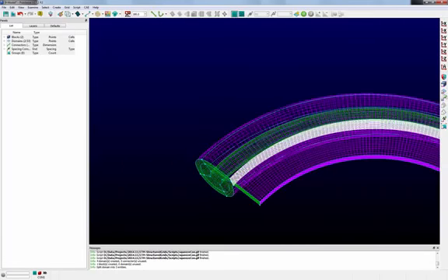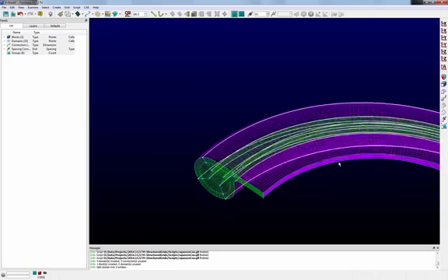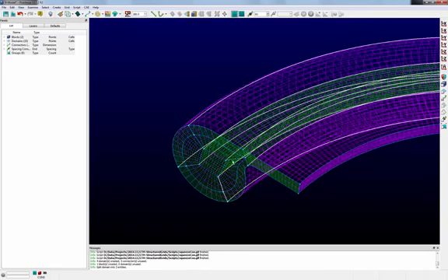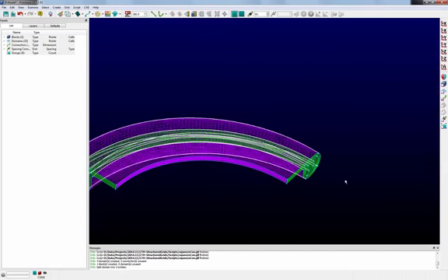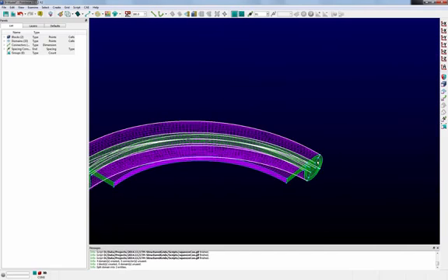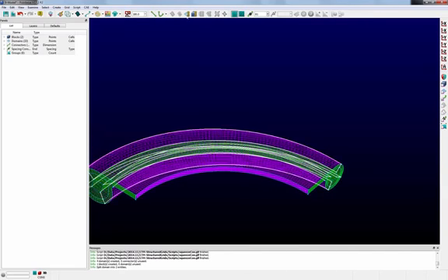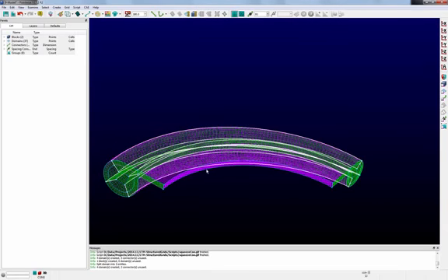And then I'm going to, again, highlight the long connectors, and then I'm going to highlight these radial connectors here. We're going to do it on both sides, and then same thing down here. And bear with me, one more connector, there we go. So now we have those. We're just going to click on Assemble Domains. That's going to create 4 domains, these radial domains there.